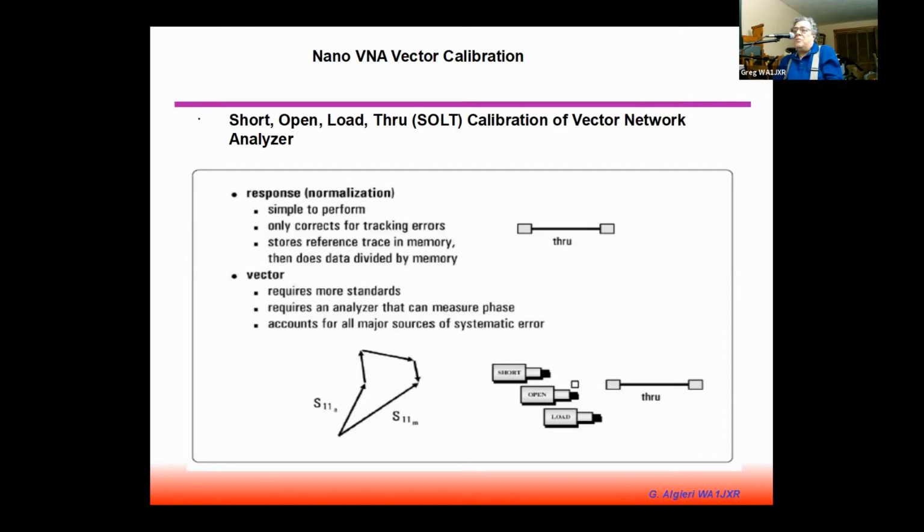and it corrects for all those errors. And this is done very accurately because all those error vectors not only include amplitude errors but also include phase errors. So it's mathematically, vectorially taking out all of those errors, and you can get very accurate measurements down to, you know, 1/10 of a dB in amplitude and probably 1 degree or so in phase, which is pretty good.